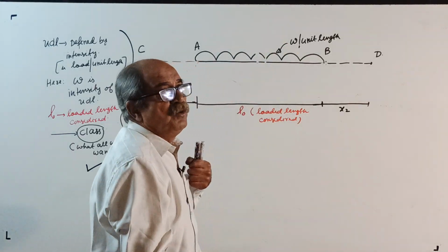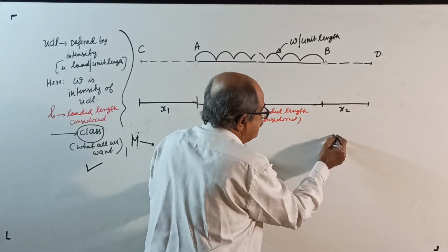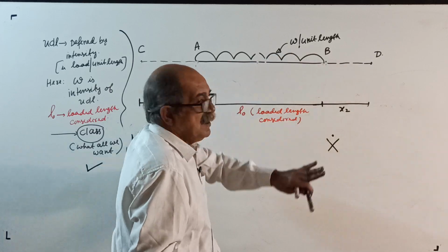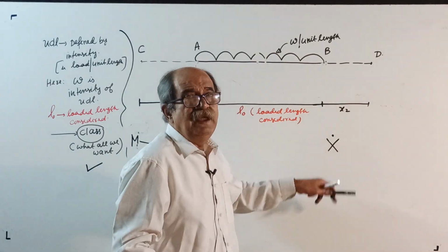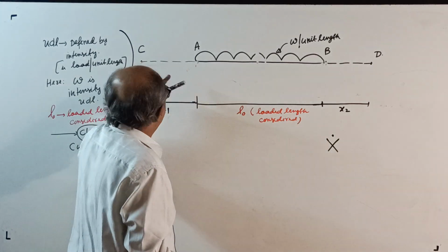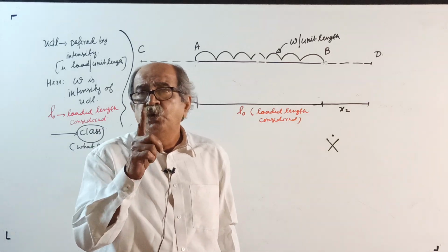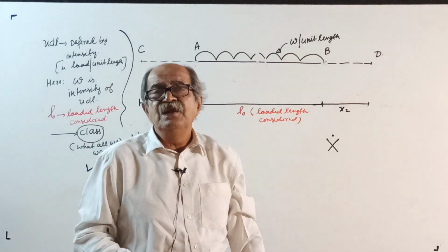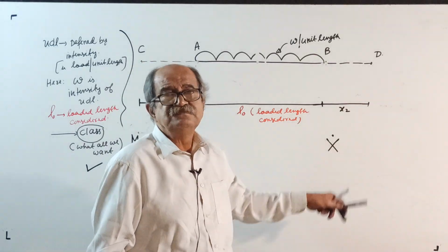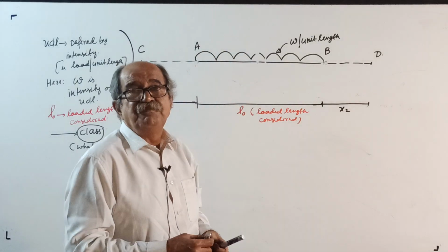Magnitude of the total load multiplied by, that multiplied I will use always like this. Moment multiplied. Multiplied by perpendicular distance from the point about which you want moment to line of action of the total load for loaded length considered.